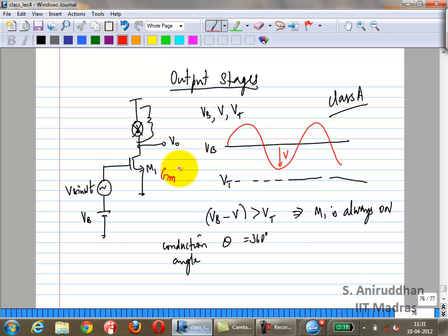you can get the nominal large signal GM. You no longer have small signal GM, you now have an effective large signal transconductance, right? You can still represent your gain in terms of your large signal transconductance. Now that large signal transconductance will be a function of V. That much is for sure. But for every value of V, you might have a different transconductance.